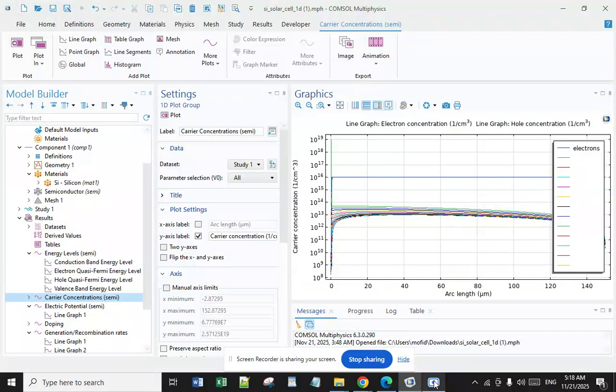The next is damage. It can result from stress-induced damage to the junction or other parts of the device, which can lead to increased leakage even without a complete failure. The next one is design implications. The first is efficiency loss. Leakage current directly subtracts from the generated photocurrent, which decreases the cell's efficiency and power conversion capability.